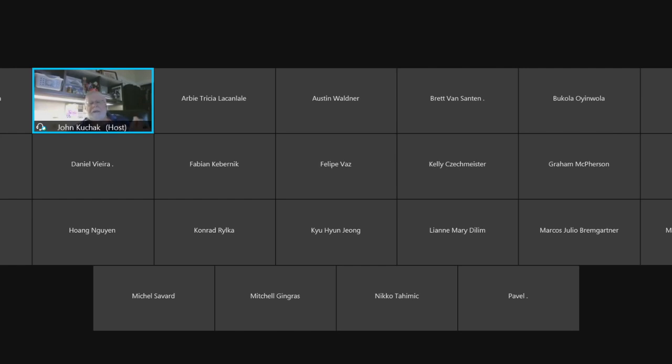You want to have that spread. Now that's 7 MPa, I just know that because it comes from industry. I've worked in it long enough to know. But if you read CSA, they tell you the statistical analysis that can occur. So those of you that have maybe worked in the industry, and you know that you're always breaking at around 38, 39, 37, 38, 39, 36, whatever, for a 32 MPa mix, that's because it's done deliberately. You have to, or else you're going to fail. And nobody says anything, but as soon as a test fails, then everybody's up in arms.